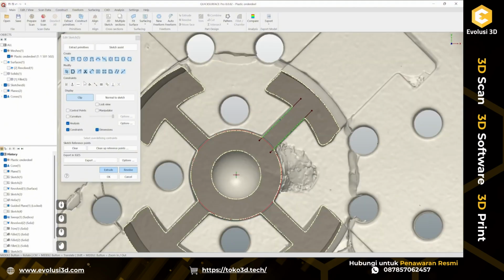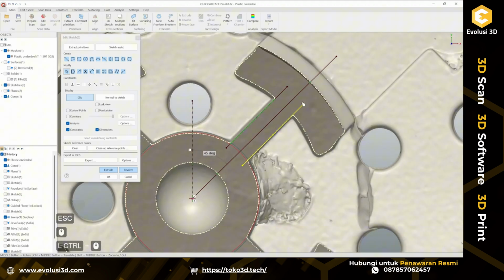Of course, we can always try to make this in logical order. And let's say I want to create this at an angle of 45 degrees. And after that, for example, I have fitted one of these entities, and let's turn this into a construction line, select both of them and mirror and see how good it fits.